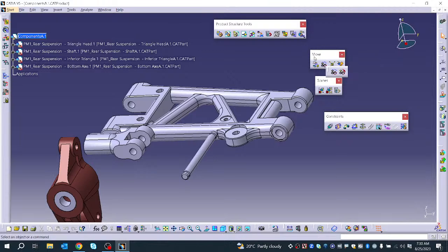As I said, the manipulation is the very manual way. Then here it is the snap. It will snap the components which you want to place together. Then next one is your smart move. It is basically used to reposition the component with the constraining.